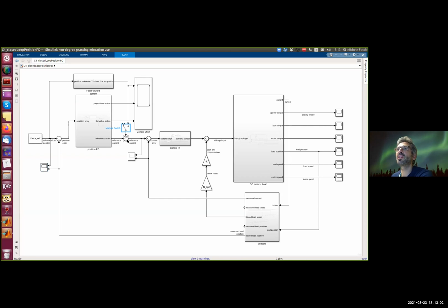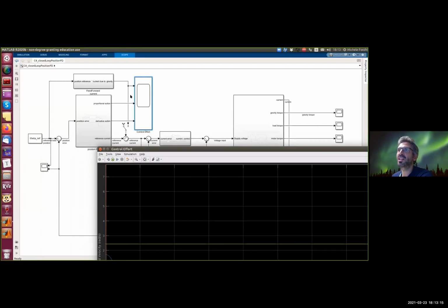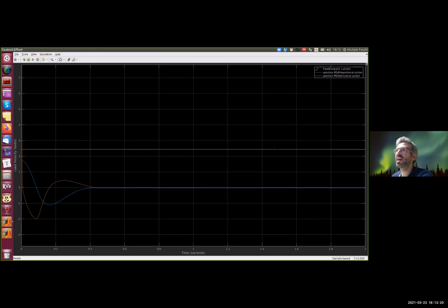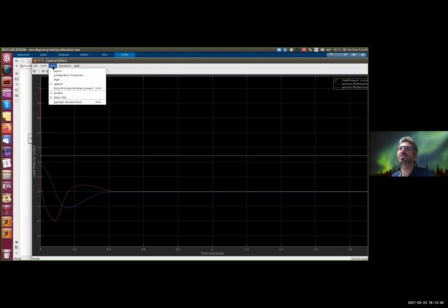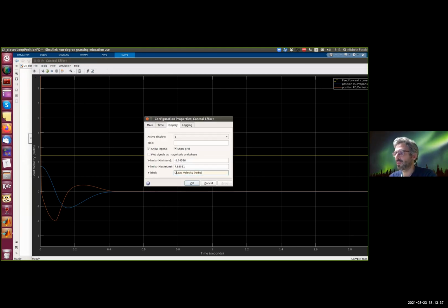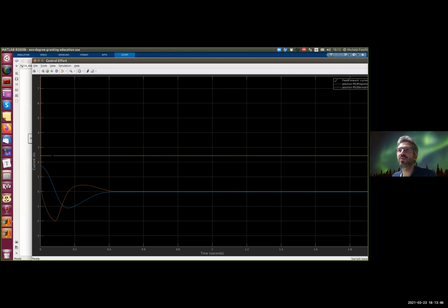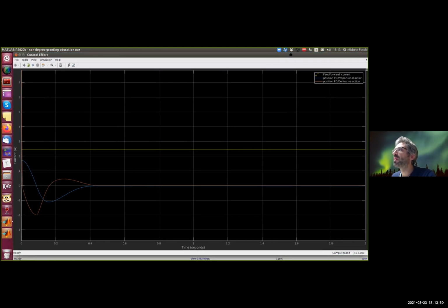We said that the feed forward relieves the action of the controller in tracking the reference. First, let's have a look at the control action. So our control action, I split into the feed forward term, which is the yellow part. Sorry, this is a current. Well, all of these are currents. We have a feed forward term, which is around 2.1, 2.5 amps. Then we have the proportional action, the blue one of the PD gain, which is 0 at the end. And we have the D action, the derivative action. It is very, very big at the beginning and then goes to 0.